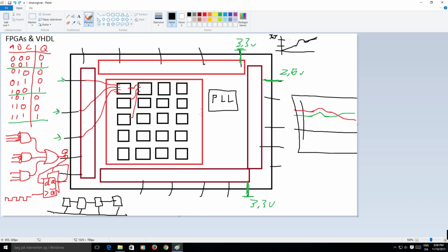You can get around that using the PLL, and we will be using that in this project also. So the PLL will take the main clock, and the internal circuitry will do exactly as the name suggests. It will lock the output to the phase of the input. So whatever you divide the output down to, it will always make sure that the rising edge lines up with the rising edge on the input clock. This of course means that there must be an integer division between these two for it to happen. I don't think we're going to look at exactly how this works internally, but we just want to know that it is there and we can use it.